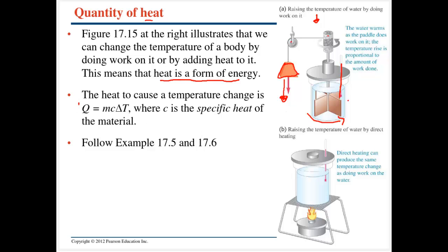So we can write this heat energy, that's going to be that symbol Q, as being related to the mass of the object that you're changing the temperature of. It's going to be related to the change in temperature. It's also going to be related to the specific heat, which is also going to be known as the heat capacity of an object. And I'll talk about this a little bit more on the next slide. It's really material dependent. So very important equation to know.